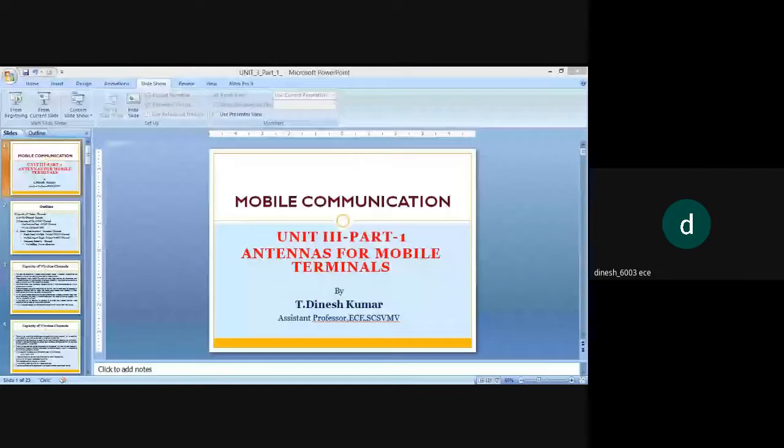So this is a building block of all the wireless channels. It serves as a motivating example of what capacity means. The capacity of the time invariant additive white Gaussian noise channel and capacity of time varying flat fading channel is given in this presentation.